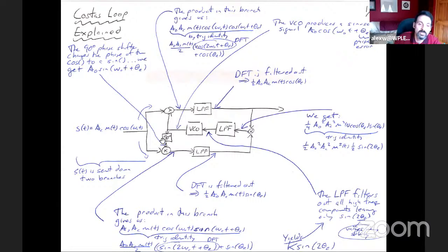This is going to be cosine, and what happens is the voltage controlled output cosine wave, it goes under a 90 degrees phase shift, so now it's a sine, okay? And what happens is it's now sine times cosine. So now what we get, right, is we get cosine cosine, and at this here, it's going to be cosine sine, and it's going to also have that phase offset, right?